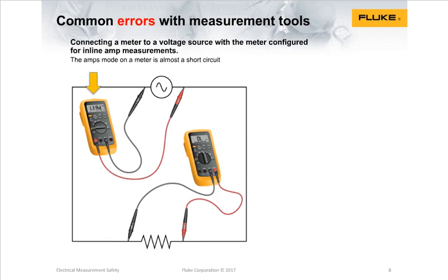You have a fuse that typically protects this. And in Fluke's case, this is a very fast blow fuse to separate the instrument from the circuit. But nonetheless, that does put it in a short circuit type of position. And if you go ahead and measure across a voltage source, it will open the fuse. So again, if you have an instrument that has a fuse, don't bypass the manufacturer's recommendations for it, because then you're violating your own safety.